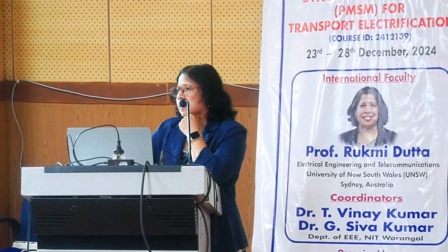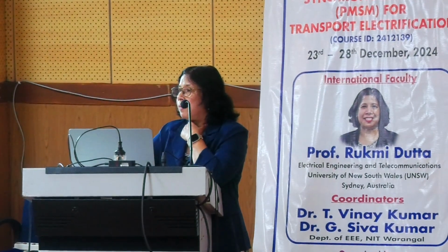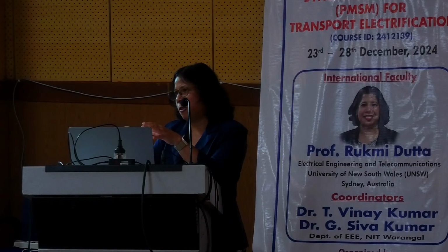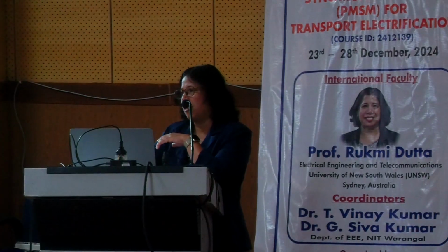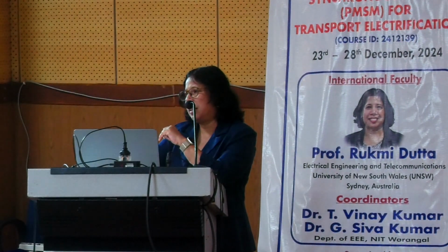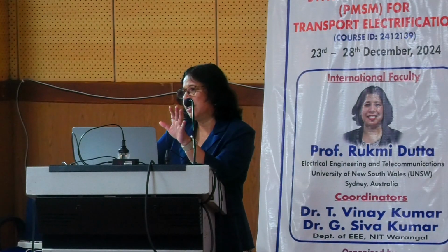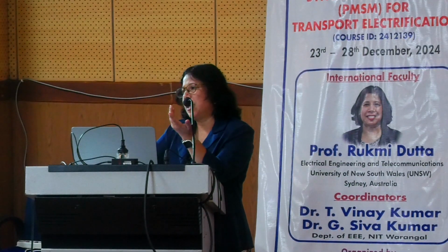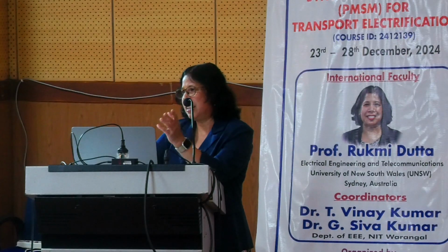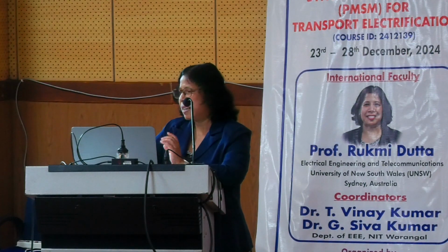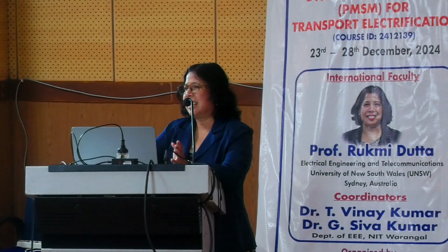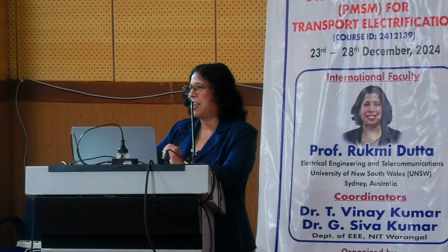Synchronism will come after. After some time the sensor will start to give us the accurate position, and then we just move to the sensorless control, FOC or whatever control we are doing. So during starting, V by F or I by F is quite a good technique to use. It's very simple and does not need tuning, so it's good. But for the full range of operation, it's not recommended.